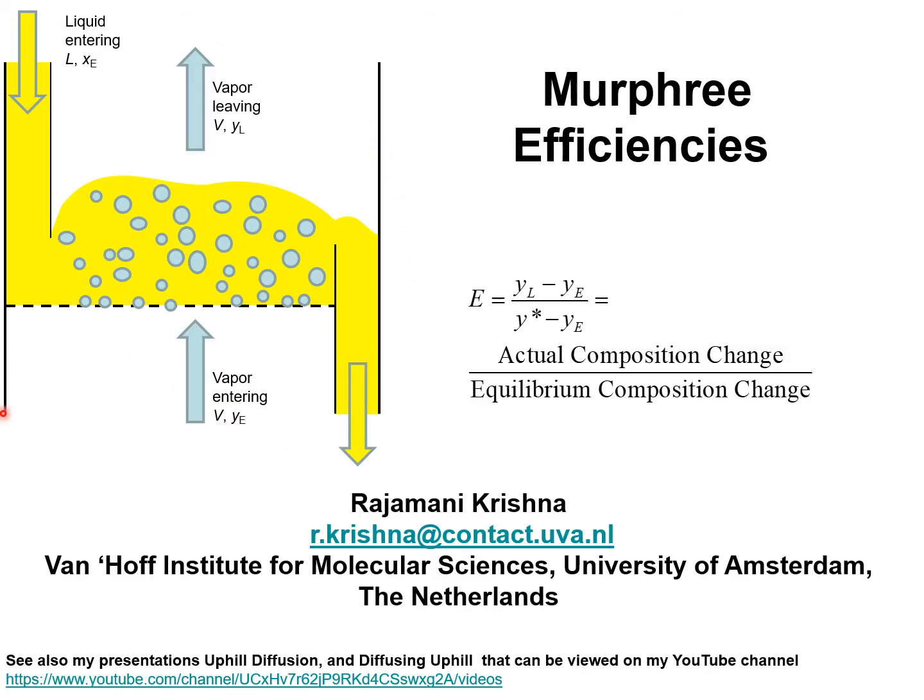Here's a schematic of the operation of a distillation tray. Let us assume that the operation is in the bubbly froth regime. Y_E is the composition of vapor entering the tray. Y_L is the composition of vapor leaving the tray. And to keep matters simple, let us assume that the liquid phase in the tray is well mixed. That essentially implies that the composition of the liquid leaving the tray is the same as the composition of the liquid mixture on the tray.